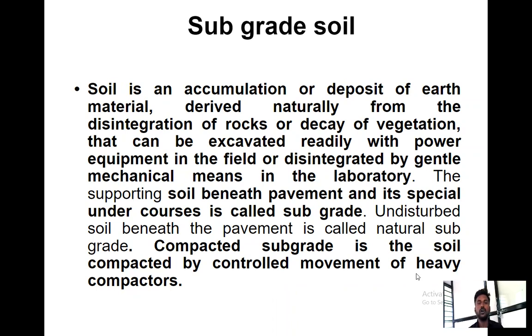Okay, for the compaction, what do we use? Different kinds of compactors or heavy machineries are there, and it depends on the type of the soil. Which kind of machinery or compactor we have to use depends on the soil. If there is a clay soil, we require a different kind of compactor. If there is a sandy soil, we require a different kind of compactor. So depending on the soil, the compactor will differ.